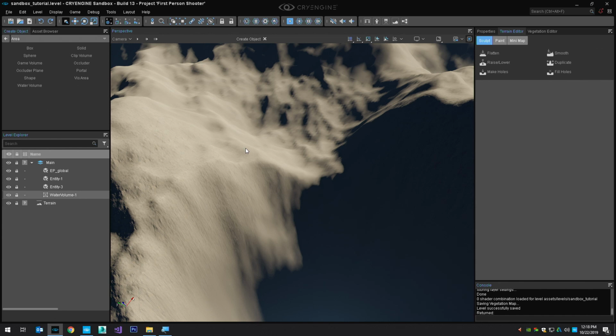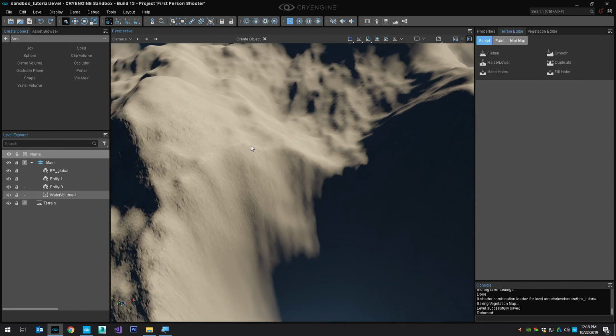And the trick to doing this is put the points of your shape, this is going to be a straight line shape, put them outside of the lake. I'm actually going to put the points of my area outside that, higher than that, just a little bit above the hill like that. And what I want to do is snap the points to the terrain.